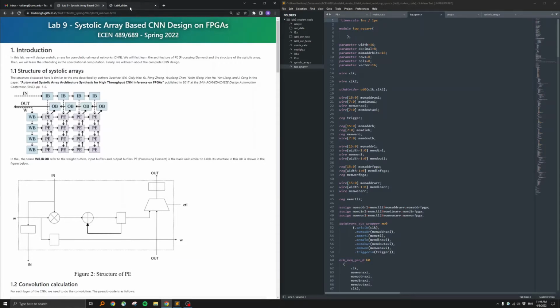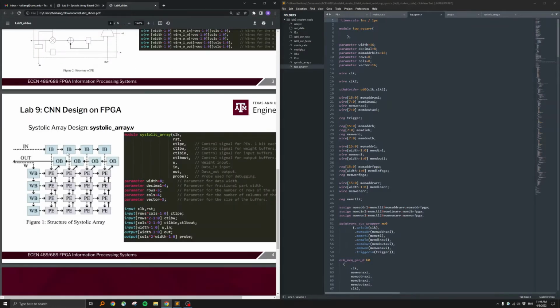So we will have to save those images and the weights as a result of the training. Those are a lot of data, right? They have to be saved into some places on the chip. For example, we have the data on the DRAM on the chip, and we want to fetch them from the memory and push it into this systolic array. This is why we need some buffers as an internal place.